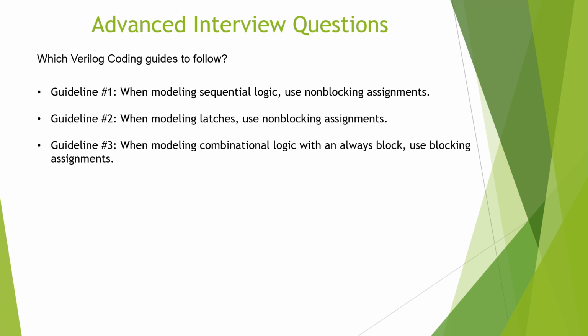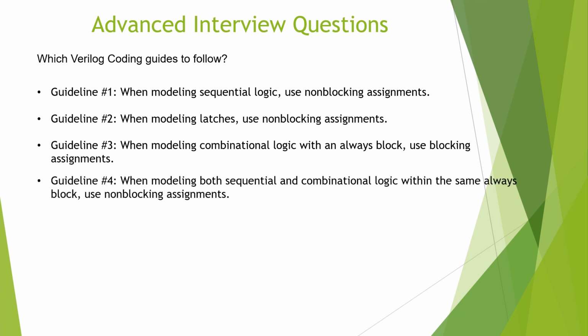And number three is when modeling combinatorial logic within an always block, use blocking assignments. So combinatorial logic is regular logic gates without the latches or the flip-flops. So when writing the code for the regular gates, use blocking assignments. Guideline number four is when modeling both sequential and combinatorial logic within the same always block, use non-blocking assignments. Suppose you have to mix sequential and combinatorial within the same always block, always use non-blocking assignments.